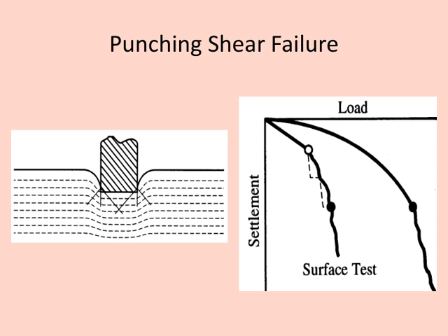We need to ensure that the shear capacity around supports exceeds the anticipated loads, especially in areas with concentrated loads. By understanding the mechanics of punching shear, we can better specify reinforcement details and material strengths to prevent such failures. So, in the context of this presentation, recognizing and designing against punching shear is key to ensuring the durability and safety of the structures we design.